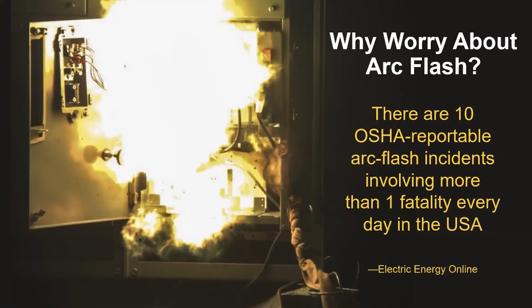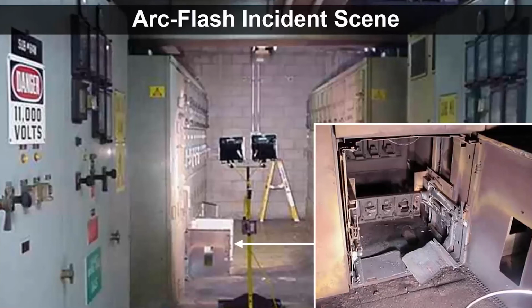And in the next slide, you can see a picture of an arc flash incident scene. And this arrangement is all post that incident. You can see there's a lighting arrangement and so on. This was all done post that incident. So apparently the incident was caused by an unsecured cover on a mounting plate, and this is the 480 volt cubicle. They also had the substation secondaries tied together, which caused an increased amount of available energy. And the estimates suggested that the energy was beyond 60 calories per centimeter squared. And just recalling what I mentioned earlier, a second degree burn is caused by 1.2 calories per centimeter square.